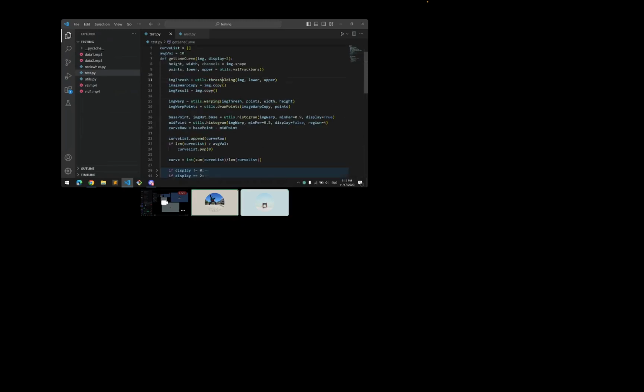There's 3 main steps that we're performing once we have the lane: thresholding, warping, and some type of histogram calculation. This is where we determine our actual curvature, our actual point of interest. So we'll look into what these 3 methods are doing. As mentioned, for calculating steering, there are 3 different operations we have to do. And we start off with thresholding first.